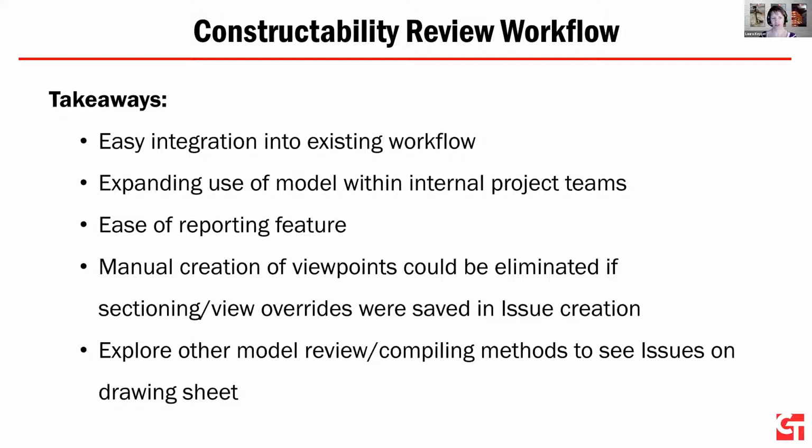It would be cool if there was a way to keep that sectioning and view overrides when you're creating the issue. We've been talking with Autodesk about this. And because I had exported NWCs from Revit models and made an NWD, the issues weren't linked to any sheets because the sheets don't exist in that NWD file.